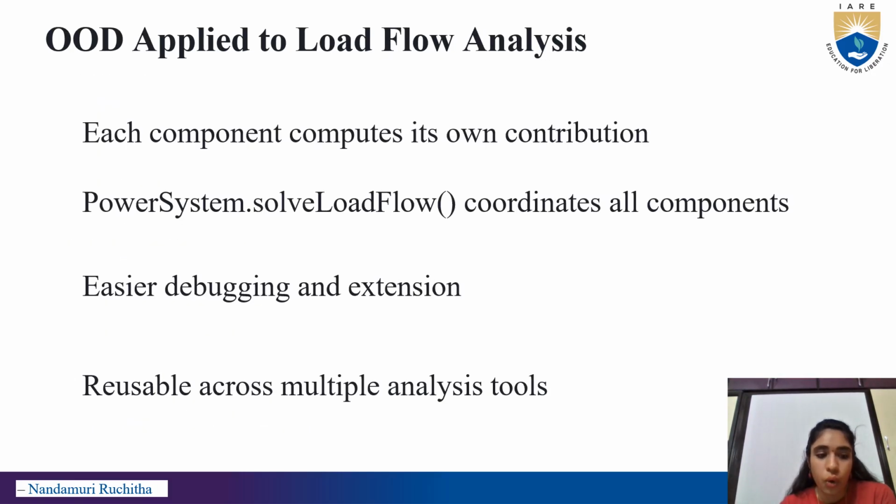Next, OOD applied to load flow analysis. Each component computes its own contribution. PowerSystem dot solve load flow coordinates all components as well as points. Easier debugging and extension. Reusable across multiple analysis tools.